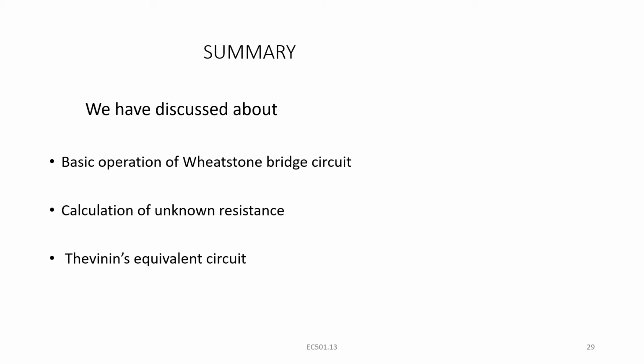If we speak about the AC bridges, we have the Schering bridge, the Hay bridge, and the Maxwell's bridge for different applications, where we are using them to find out the unknown resistors, the value of unknown inductors, the value of unknown capacitances. We can also find out the insulation resistance. Using the Wien bridge, you can also find out the unknown frequency.